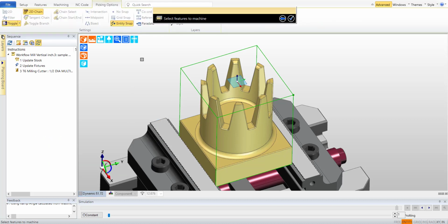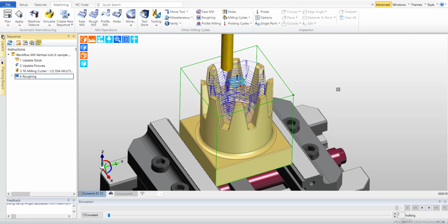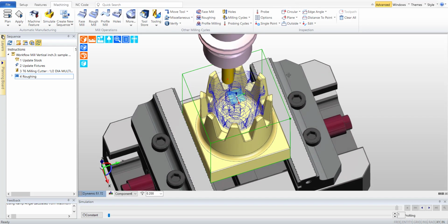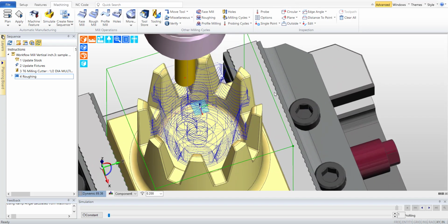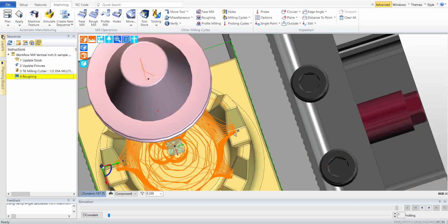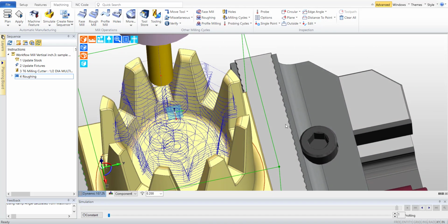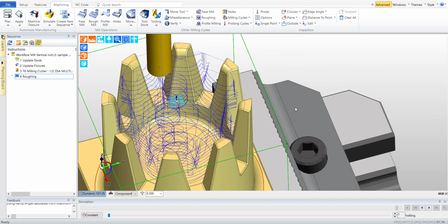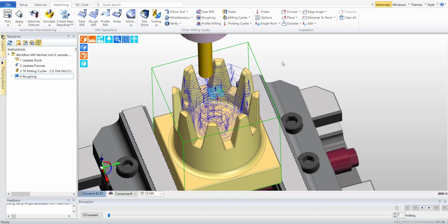and what I'm going to do is select the solid because we really don't have a decent feature here to machine. And then what I'll do is contain it within a boundary, okay? So we'll select the outside. And you can see it does machine that, but we also get it coming out outside these voids here. There's really no good way to prevent that, because if our boundary was smaller, we wouldn't hit the outer taper on the top of that part.